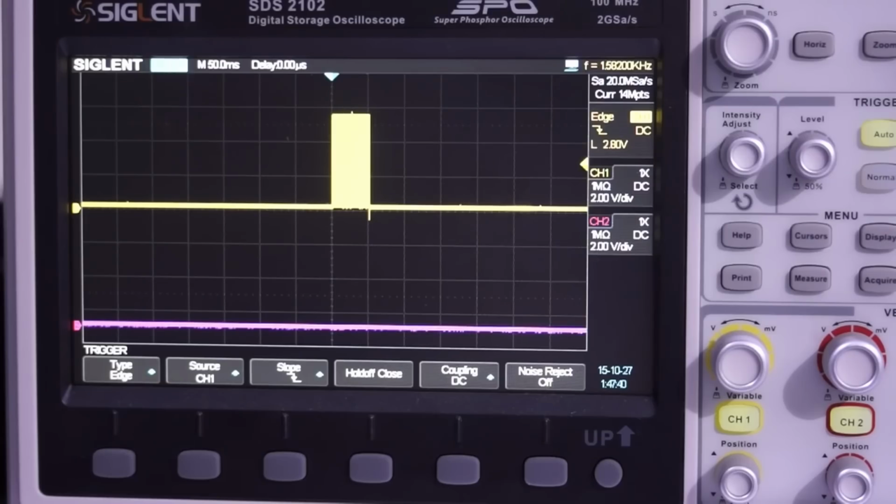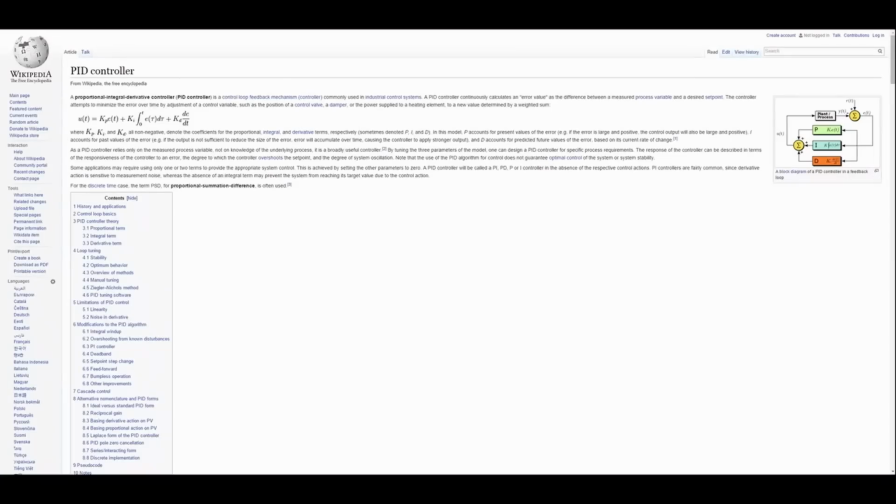We learn that the on-off controller is simple and okay if the control loop is much faster than the reaction time of the system. And if the switch is mechanical, we have to take wear and tear into account. If you Google, you quite often find the expression PID controller. What is this? How does it work?